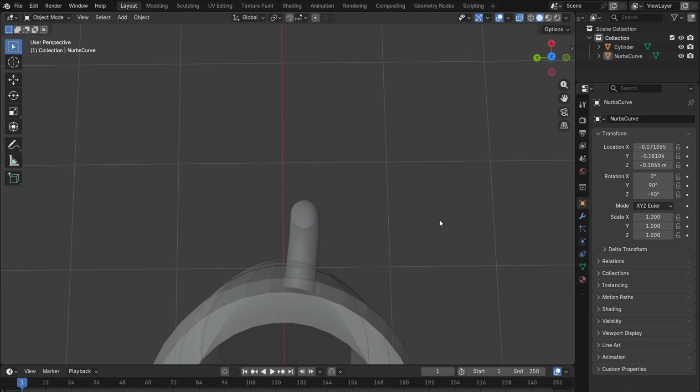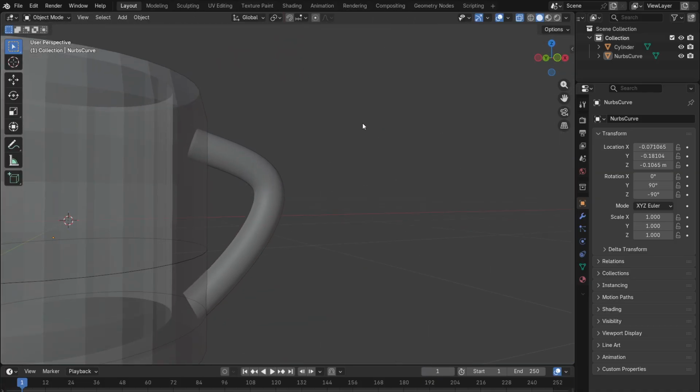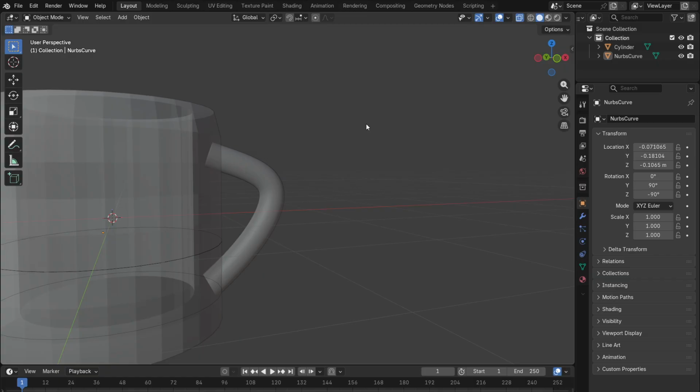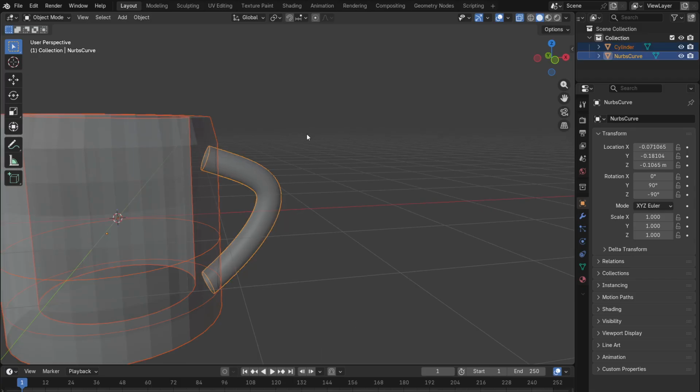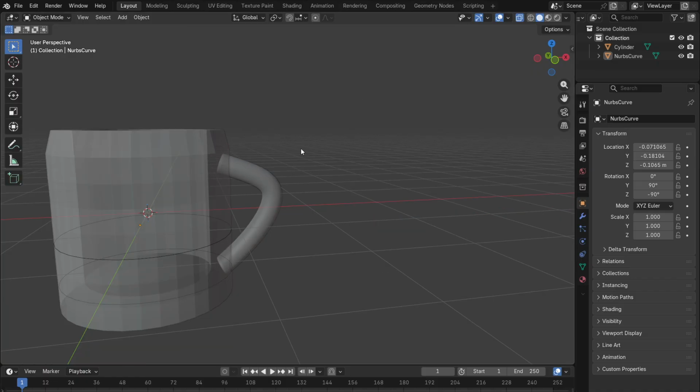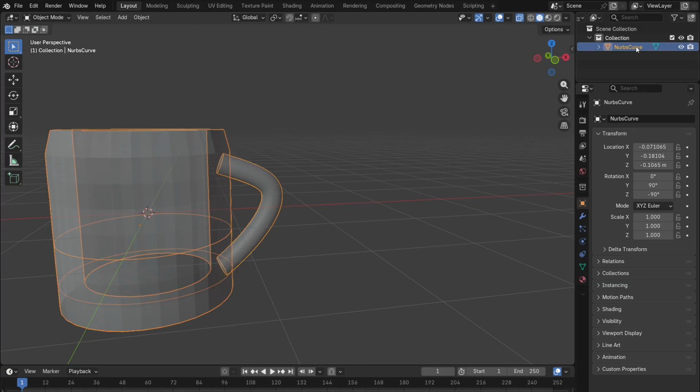It's not faulty actually. It's a very good geometry, but I'm not using fill. Fill is a little bit dangerous. After you do it, it's difficult to manage your polygons, your lines, even your vertices sometimes. So that's why I avoided it in this example. But you can also get the resources and try fill. Just press F. Select the opposite sides of the two objects, and then press F. It's going to fill the geometry with mesh geometry. So that's your object. Select them, Control J.